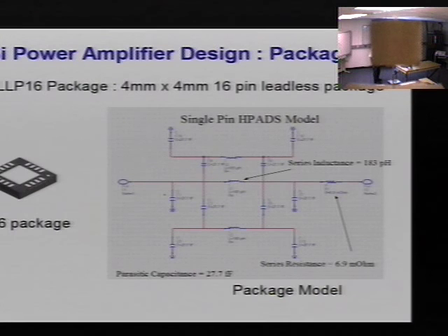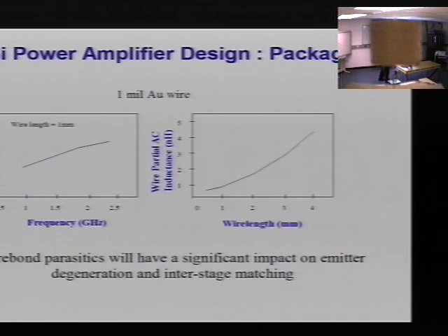Probably very good for us in terms of having stability for an amplifier, primarily because a lot of this creates unnecessary feedback, which you haven't compensated for, and then you end up with an oscillator. So you have to be very careful about that. Spend a lot of time looking at wire bonds.